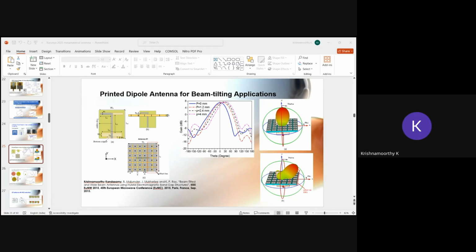Yeah, MIMO antenna, we showed two examples here, the last two designs we showed for the MIMO antenna. In the MIMO antenna, mainly the metamaterial structure we are using is for isolation improvement between the array elements. So a band gap structure or some frequency selective surface can reduce the mutual coupling and improve the isolation. So we can use metamaterial structures in the MIMO antenna.